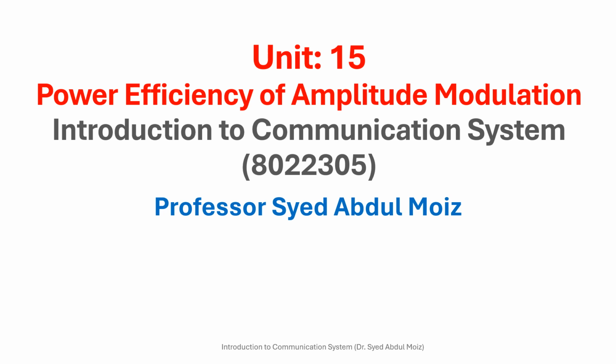The efficiency is determined by the modulation index, which is the ratio of modulating signal amplitude to the carrier signal amplitude. Maximum power efficiency in AM is achieved at a modulation index of 1, corresponding to the condition where the sideband power is maximized without causing overmodulation.